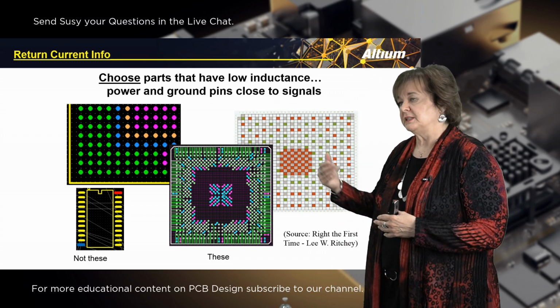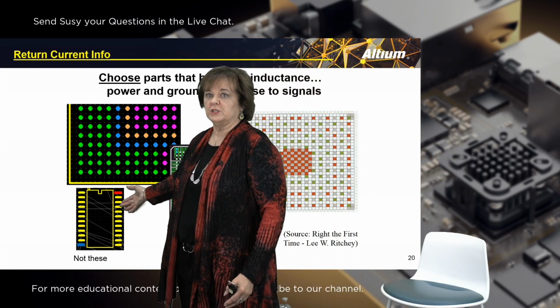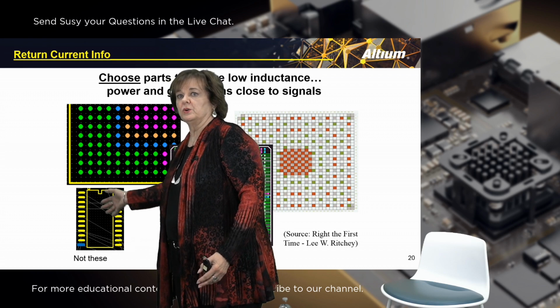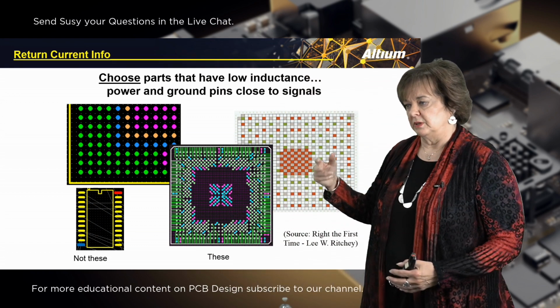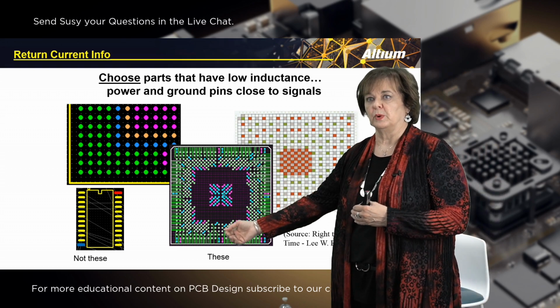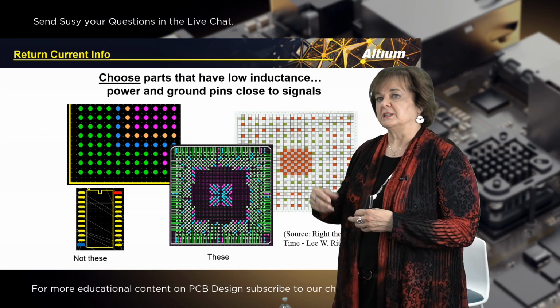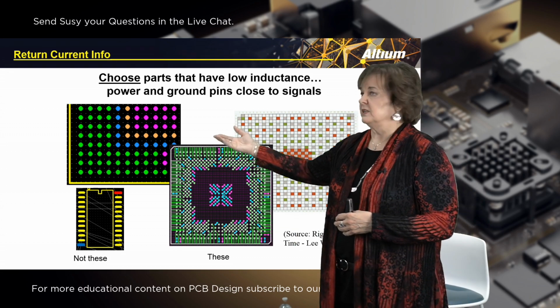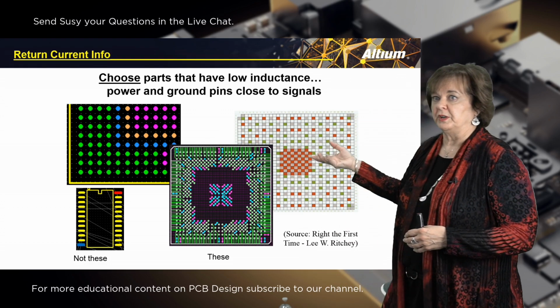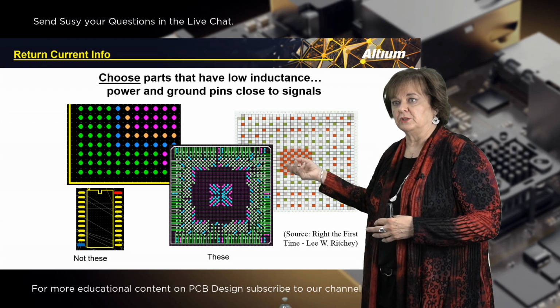But now if a signal routes into the upper regions or the lower regions here, it has a long path for the return current to go and find the ground pin or the power pin that it's returning on. And so that's not as good a method to use as opposed to using something like this one over here, where the signals all have a close power or ground pin to return on.